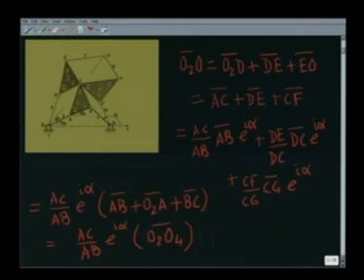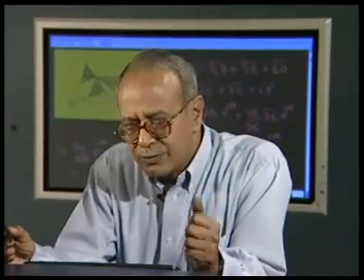So, though this is a single degree of freedom mechanism, all of the other points move as the mechanism moves, but the point O never moves. Just now we have seen that in the 10-link planar mechanism with specific dimensions, there is one point which was not moving, though the overall mechanism had a single degree of freedom.